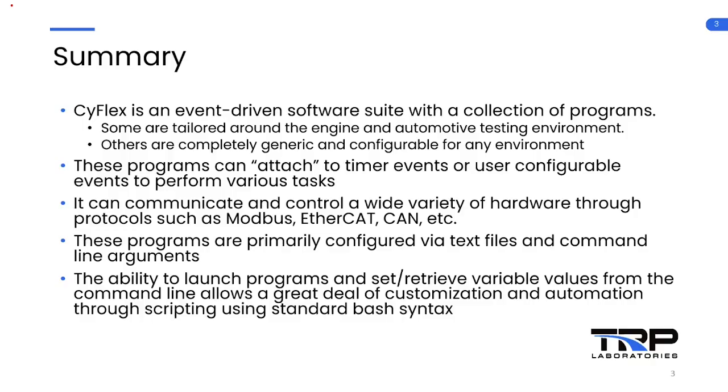You can create a string variable that's going to contain that part number or a test ID or something like that. And whenever you start the test, you can automatically create a directory structure, as well as automatically launch a data logger, and then automatically run the test. And after it's complete, anyone who wants to see that data, depending on how you set it up, may only need to know the part number and the serial number in order to know where that data is.